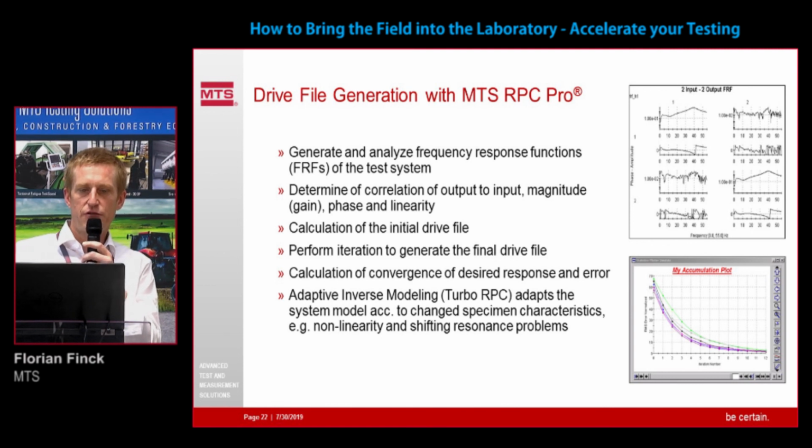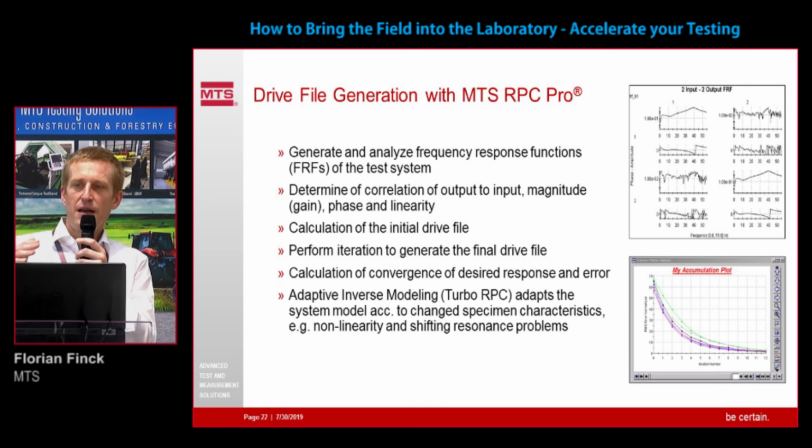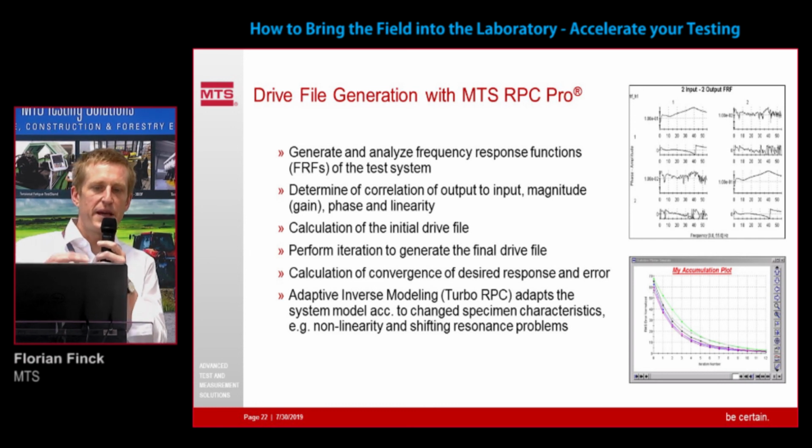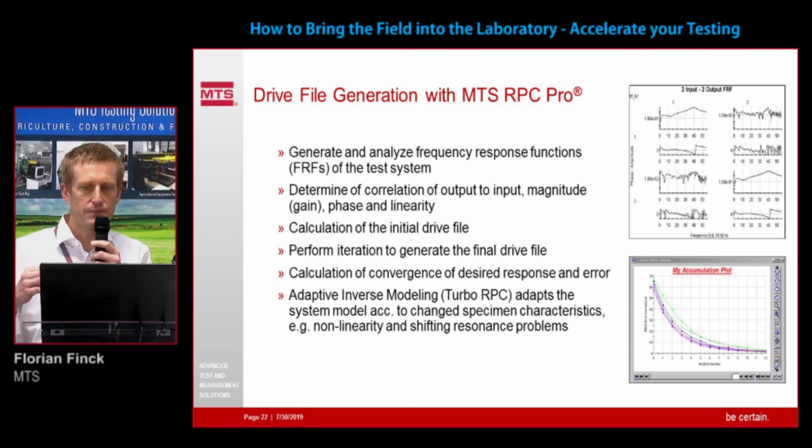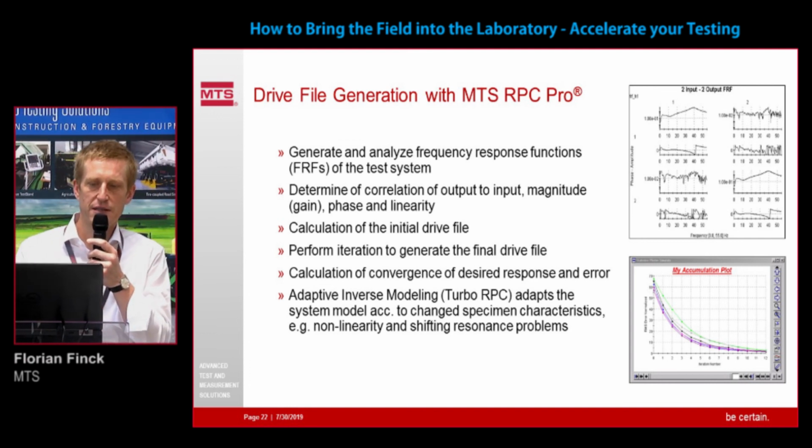Then we derive and calculate the first and initial drive file. We're playing out the drive file with a relatively low gain. And then we see how the response plays out compared to the target data. And then we're making corrections on the model in an iterative process.